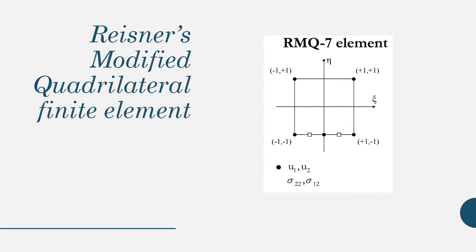In one facet, the facet that is shown below, there are 3 displacement and 2 stress forces, which allow it to be sufficient to represent fracture problems. When this facet is directed to the crack lips.